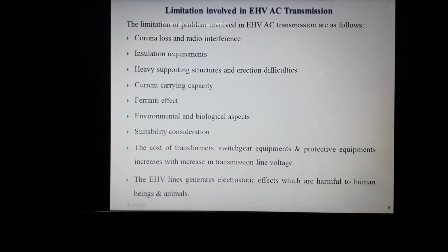The environmental and biological effect. The EHV lines generate more electrostatic effects as compared to HV or normal voltage, which are harmful to human beings and animals. And suitability consideration is also another disadvantage or drawback of this EHV transmission. The cost of transformers, switchgear equipment, protective equipment increases with the increase in transmission voltage.